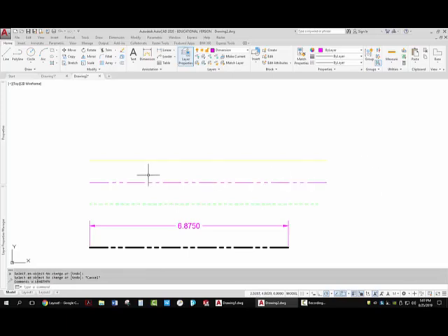To use the lengthen command, however, I just started a little bit off base. I started by selecting a line. With the lengthen command, you just type lengthen, indicate the total length you want. I'm going to type 3.875, enter. Now I'm going to pick the line I want to lengthen, which in this case is shortening it, but it's the same command. Now that line has been changed to 3.875.